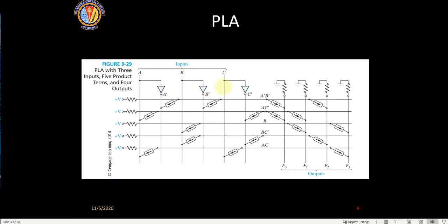Similarly, with these 3 inputs, if the oil pressure is low but the switch is off, then even if the oil pressure is low, you should not switch on the pump, because the switch is off. So certain real life conditions are already fixed here. These are the inputs coming from the sensors, these are the outputs. Essentially we know how it is to be programmed, and once it is programmed, you just connect the inputs and the outputs. There is no dynamic changing of the functionality here.